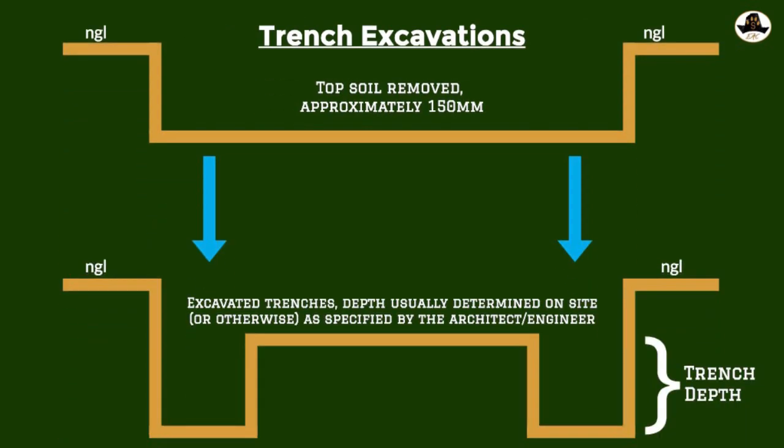So after topsoil removal, we then go on to excavate the trenches. We excavate the trenches, and the designer, who can be the architect or the engineer, specifies in their specifications on their plans or general specifications how we're going to measure the depth and what the measurement is for the depth of the trench.